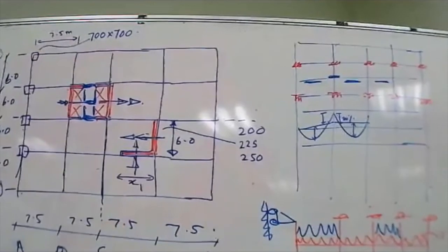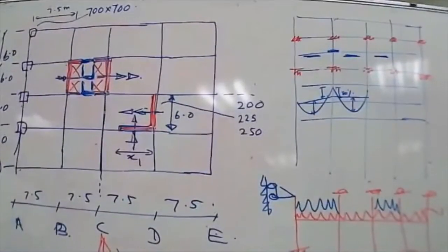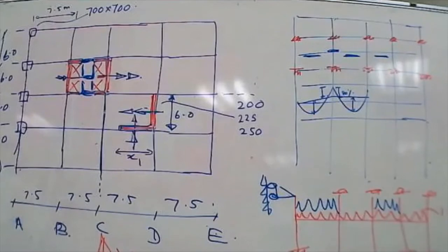So if you have provided reinforcement at about 75 millimeter centers, that is the rule I always use. For about 0.6 meters, I use T8 reinforcement at 75 millimeters. Automatically, you will find the confinement is high. Because the confinement is high, the behavior of the building where the redistribution has been undertaken and where no redistribution has been done, both will be the same.